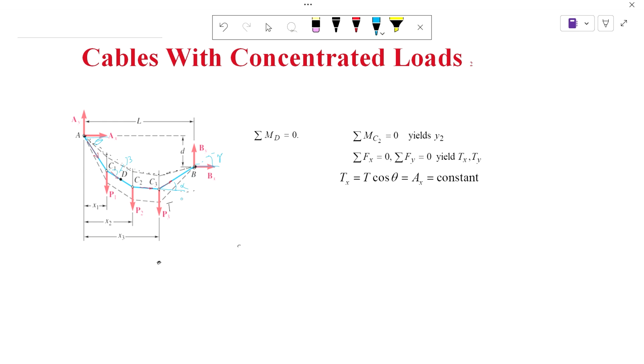It's important to determine because if you change the angle, as you've seen before with the vector, you have a magnitude in that direction. If they change too much, then the tension could become too high. So it's important to know this configuration, and usually the engineer will put this down for the architect or whoever is building the system to know what is the angle of this tension with respect to the fixed point. Obviously, you have to know the distances from each load to the point, and then you can do the thing that you've known all this time.